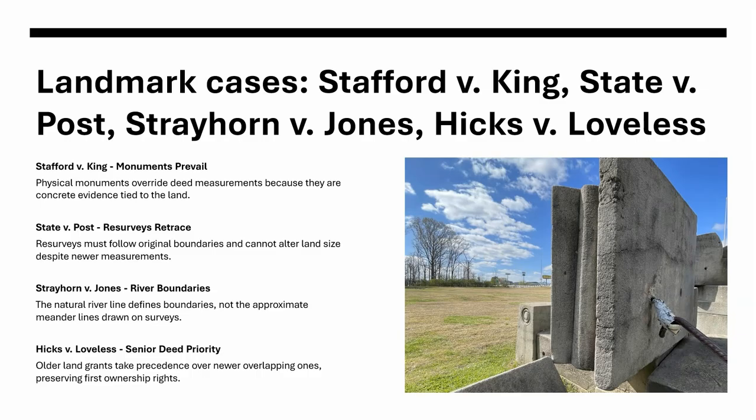For drafters, this means you cannot straighten a river on a plat just to make it look cleaner. You must represent it as it is, meanders and all. If you delete a bend, you have misrepresented the boundary. That is why we say again, when you draft, you are not just making a picture. You are preserving the truth of the land for future generations.